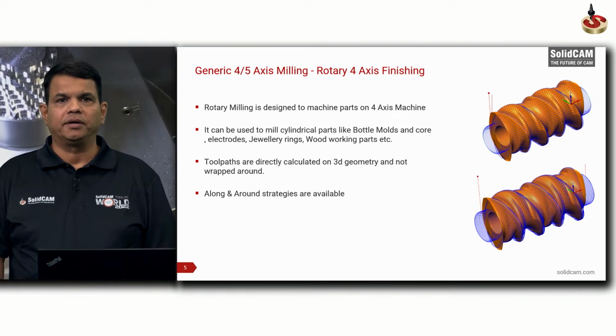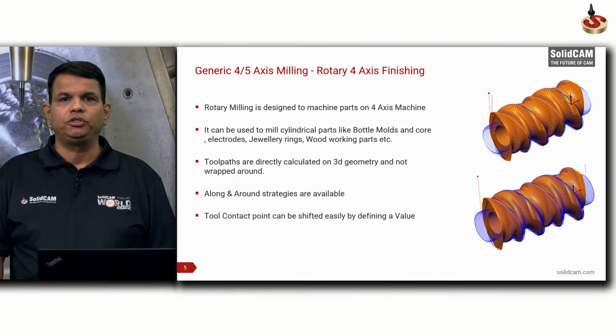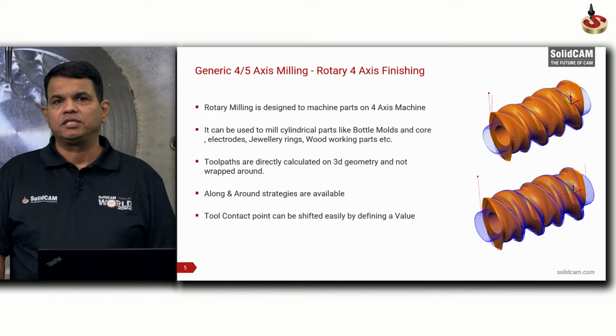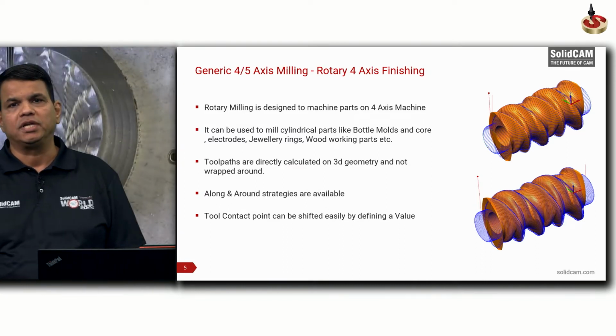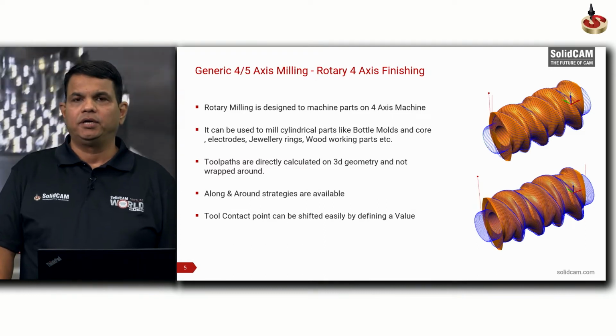Strategies that are available are along and across. You can also shift the tool axis by defining a value, and you can use the tip of the tool or the edge or the side of the tool to machine the part in rotary.